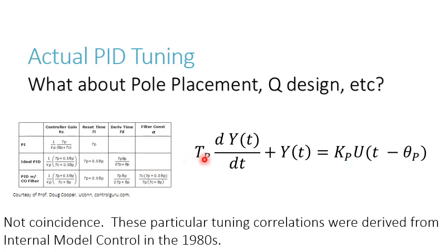The process time constant and the process gain and the process dead time, these are physical features of system responses. We saw an example in that video where the technicians were actually measuring them, and they took the plot into MS Paint and measured out the time delay, and they measured the gain and they measured the dead time. So these things are physical features of reality. It so happens that this model was found to match these measurements and use those type of measurements that are frequently found in system responses. And as a separate effort, many sets of empirical formulas, such as this set here, have been come up with that come up with good factors for your PID control, good parameters.